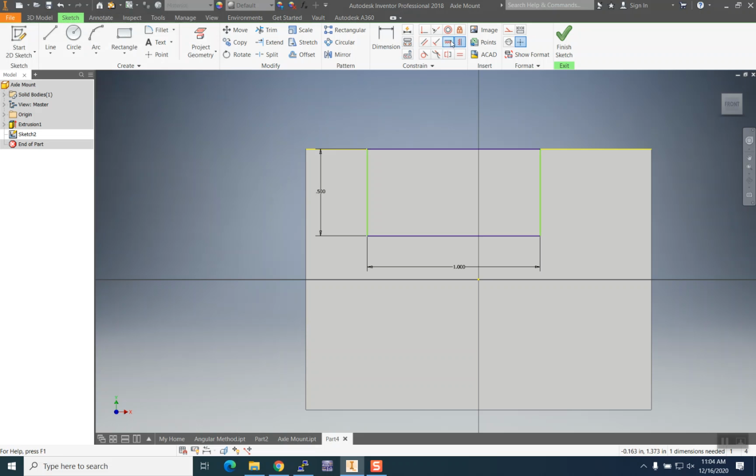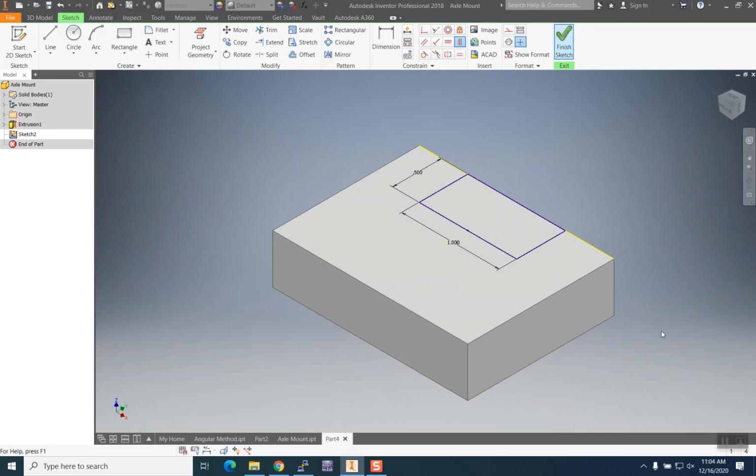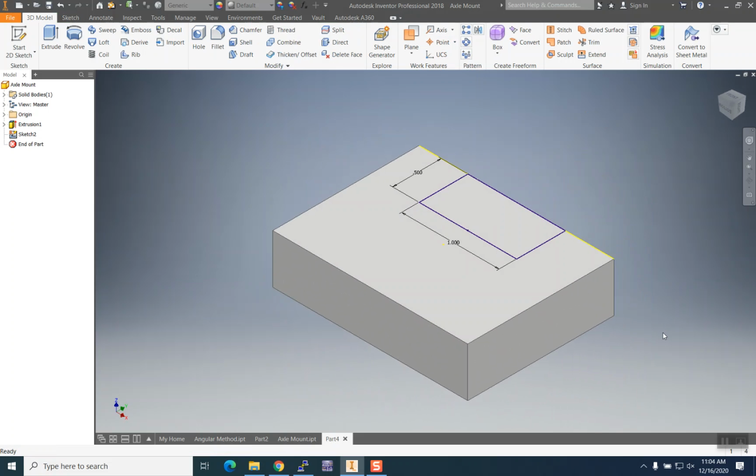We're going to cancel that. Geometric constraints allow you to make the midpoint of that line directly above the center of the original rectangle. And that's more efficient because if for some reason you made a mistake in any of the geometry or in the modeling of the base, using a geometric constraint will allow that to fix itself when you fix the dimension.